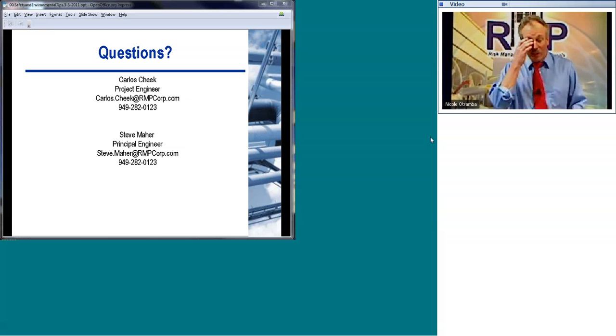Yeah, one of the things, I think it's on your list, Carlos, is basically the overall configuration of a platform or some sort of offshore facility. If you're looking at onshore facilities, a site layout diagram shows where key equipment is, especially key safety equipment, gas detectors, fire extinguishing devices, and other protection features. You want to know where those are during an emergency. It's also very important during the design of the facility.